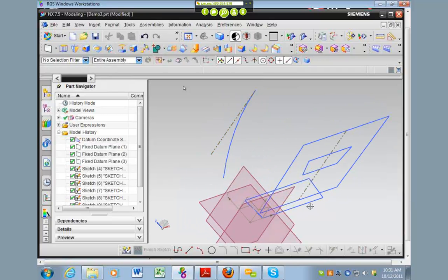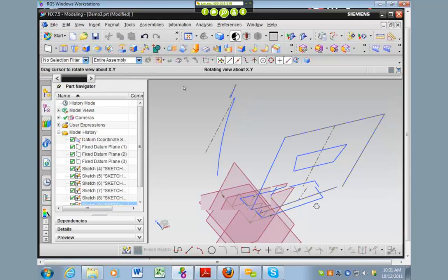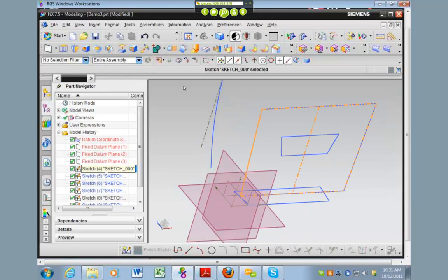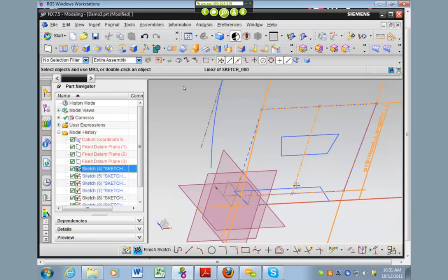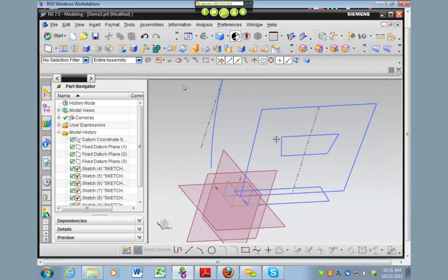Okay? And I've made these sketches parametric. So I first actually made a sketch, this guy, that is a bunch of reference lines and then 1 solid line. Or what you could do is you could just make reference lines of the shape, because this is something else important, you're going to want to make 4 different sketches. You're going to want to make each of these lines their own sketch. And I'll explain that right now.